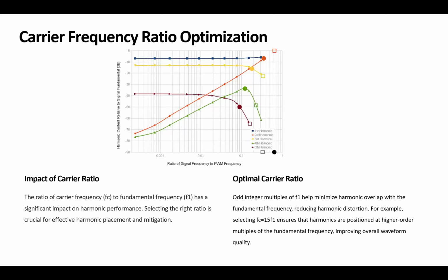We said, okay, by using a PWM in a way, like for example, having a triangular waveform as a carrier in the PWM, we already are able to eliminate the even harmonics, the even multiple of our fundamental. So that's something that we get when we choose the carriers as we chose in our previous session. We also learned because of the characteristics of the Fourier series of a square wave,